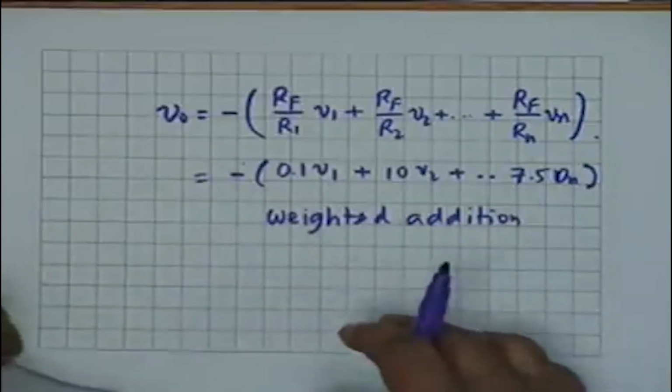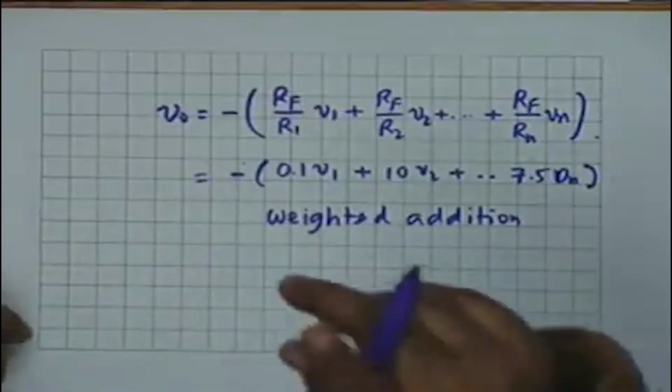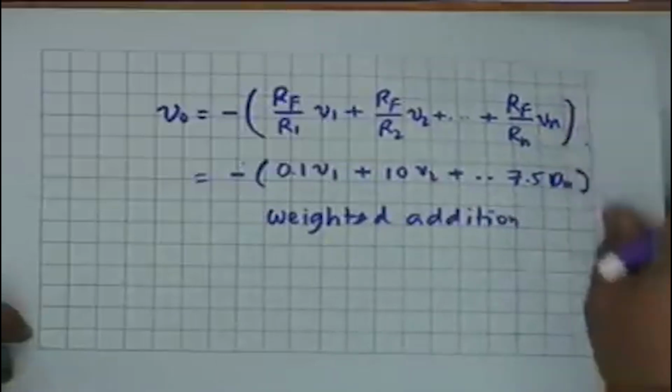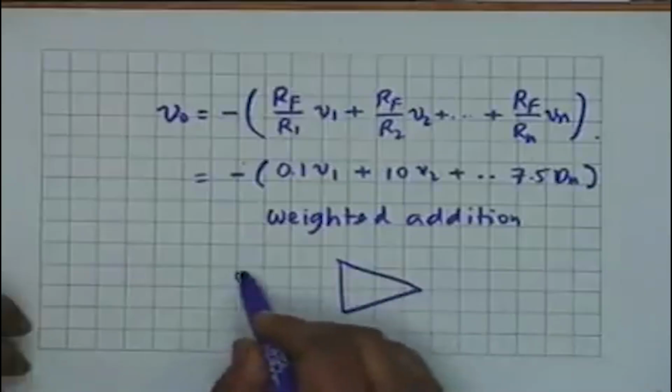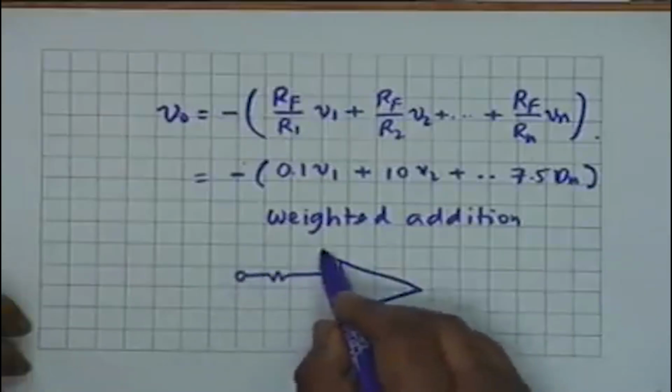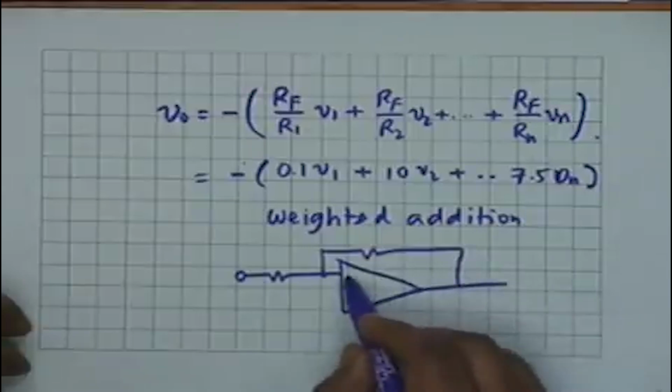What you can do is, let's find an alternative solution first. Suppose I am stuck with this. Let's say I have a chip which does this, and I want to use this chip. There is a negative sign. I want to change the sign. What do I do? That is correct. You take an op amp with a -1 gain, which is simply this op amp.